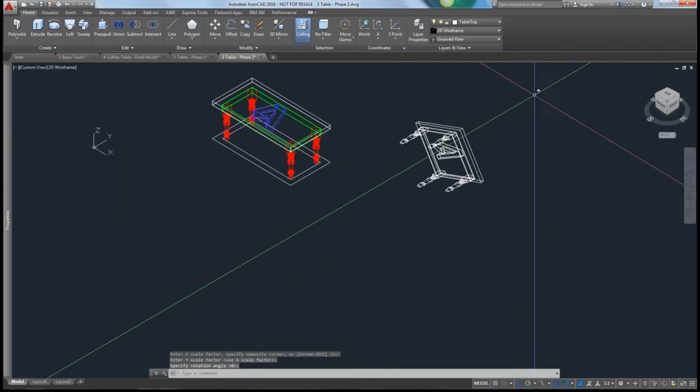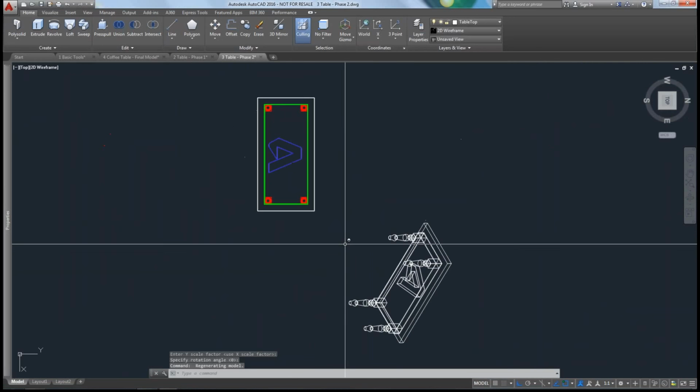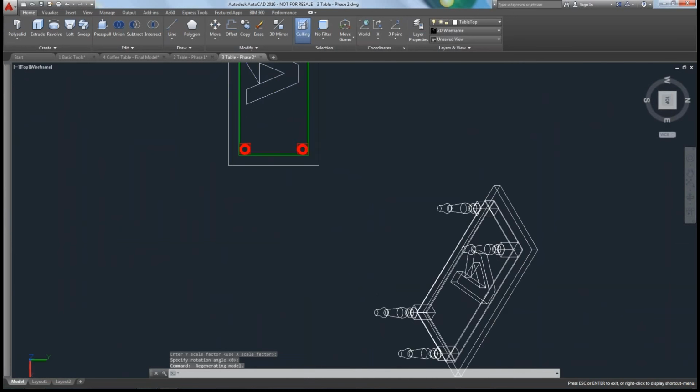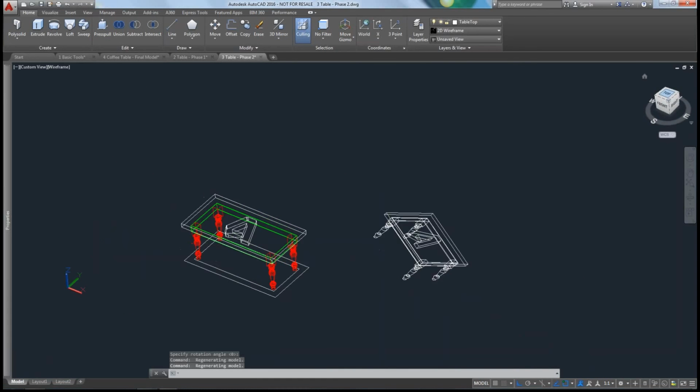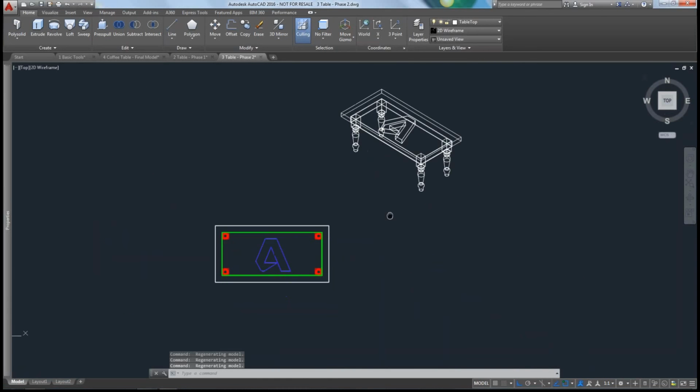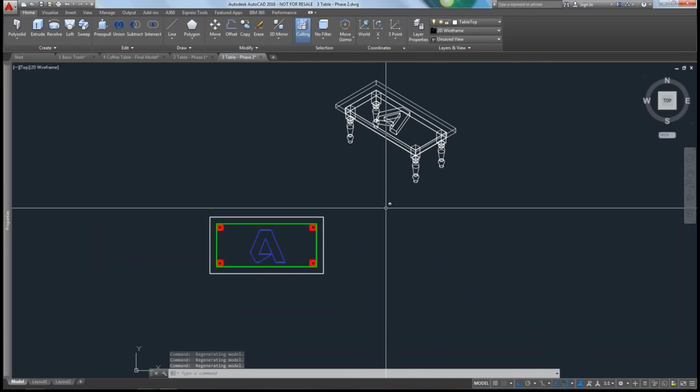See how it's elongated, it creates exactly what I was looking at in the view I was in. It creates one single piece of 2D geometry. There are other commands, again when we dive deeper, that will allow you to create third angle projection views, or your top, side, front, and isometric views, in paper space so you can actually annotate your 3D models.